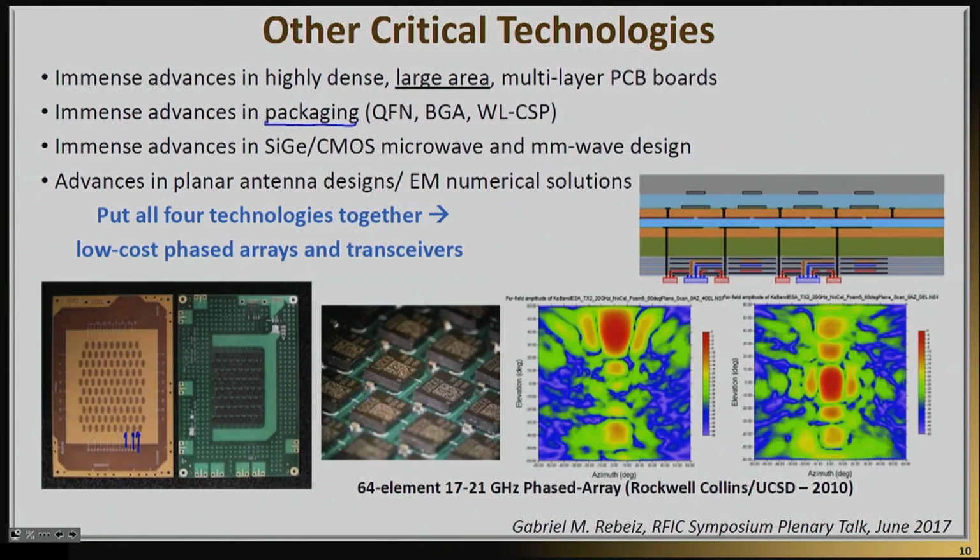I already talked about, in general, the silicon and CMOS advantages. Essentially, it allowed people to push their designs to the microwave and millimeter wave range. Just to give you an idea, 20 years ago, it would be very hard to find any CMOS process that will give you an fT of a transistor that would be in the order of a few tens of gigahertz. Now you can actually exceed 100 gigahertz. And so that means that the silicon people came up with this amazing technology to allow you to design microwave systems at a very, very low cost process.